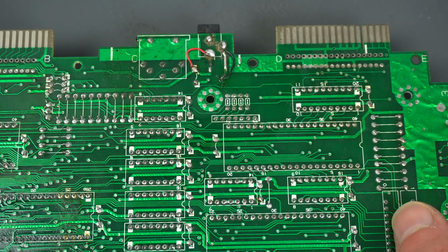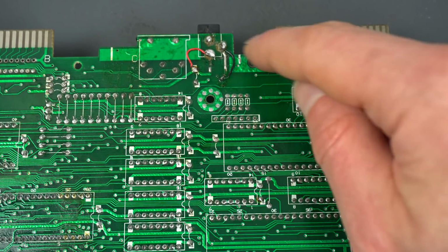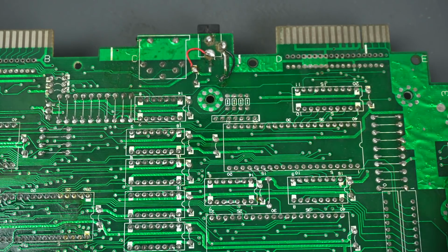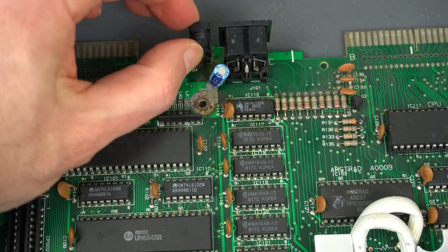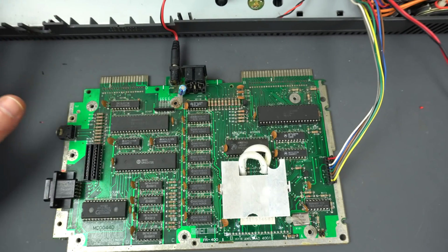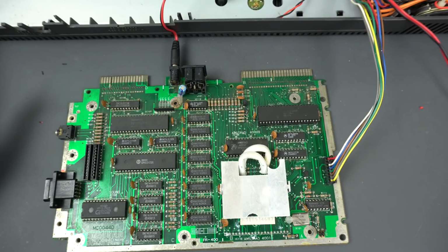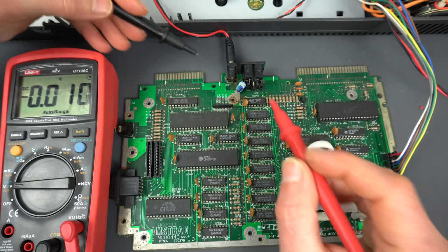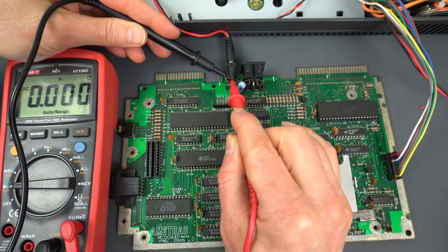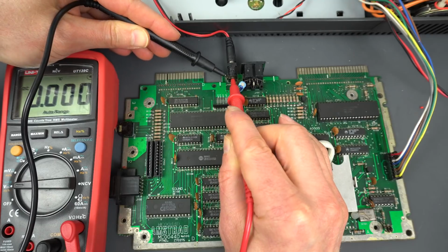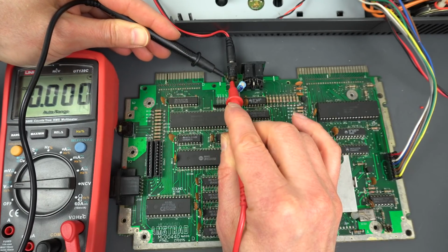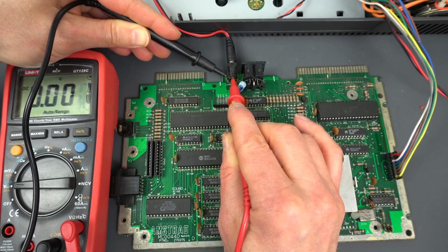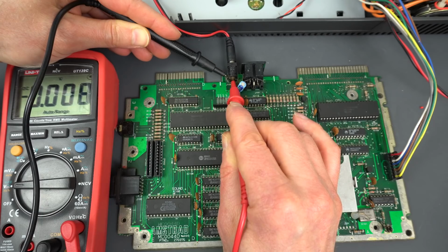All right, that's still not super pretty because we're missing the pads, so really those blobs of solder are there more for a mechanical reason than for an electrical reason. It actually doesn't move anymore. Okay, so first I just want to see if it draws any current. Still doesn't draw any current. So even though the switch is not on, we should be able to see 5 volts difference between this and this. And we're getting 0. Yeah, this DC jack, I didn't want to take it out because there were the remnants of one little pad, but I think it's just not working right.